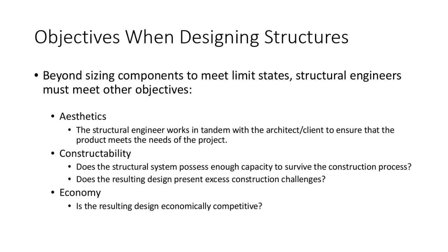As a real world example, take some of the curved box girder bridges that serve as overpass interchanges in Charleston, where 64 and 77 and 79 all interchange. Some of those structures' worst case stress state is not when the structure is complete, but during construction, when it had 8 inches of wet concrete on it and the concrete wasn't composite with the deck. So it's one of those instances where if it survives construction, it'll survive its design life. So you have to understand that process.